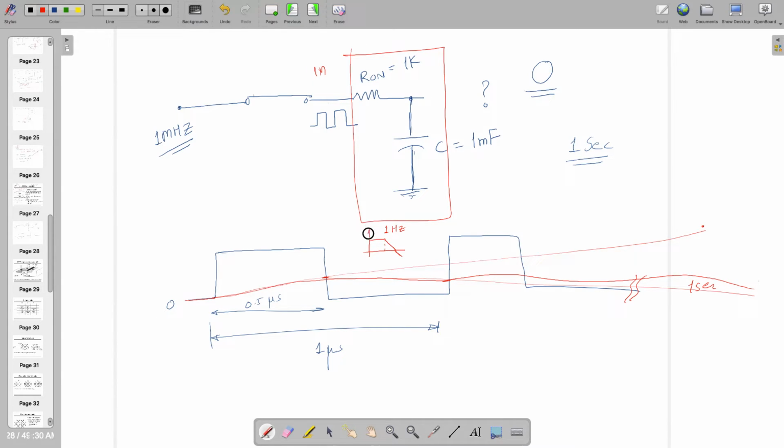You can see here and you can say magnitude with respect to frequency. What does it suggest? That if you are at 1 mega, the magnitude VO with respect to VA will be much lower than what you are expecting, right? Or it will be attenuated by minus 20 dB per decade. Yeah, you agree with this one?